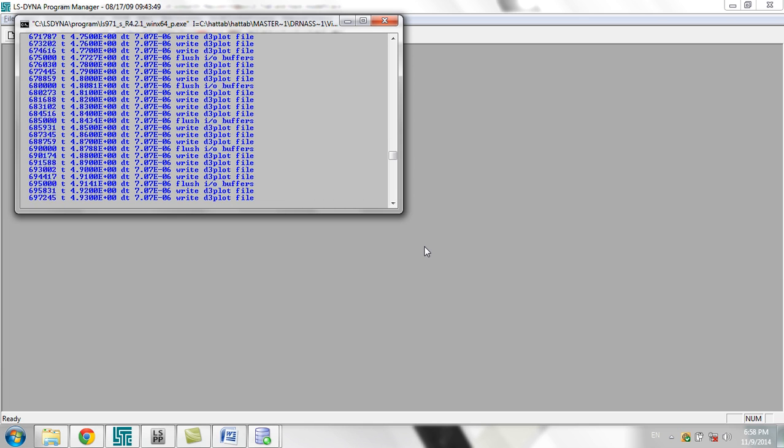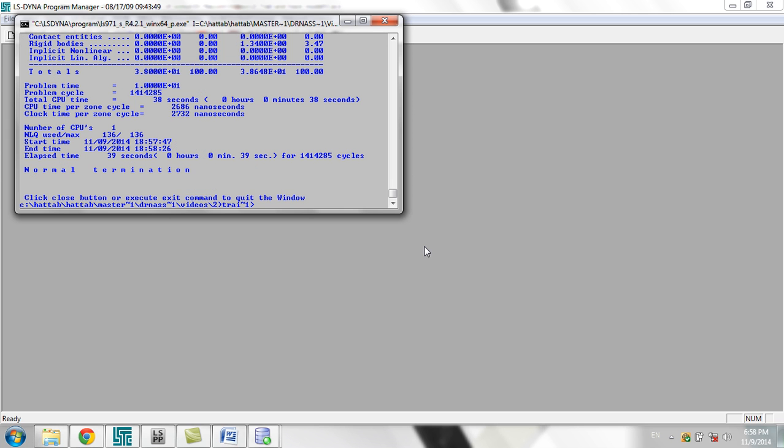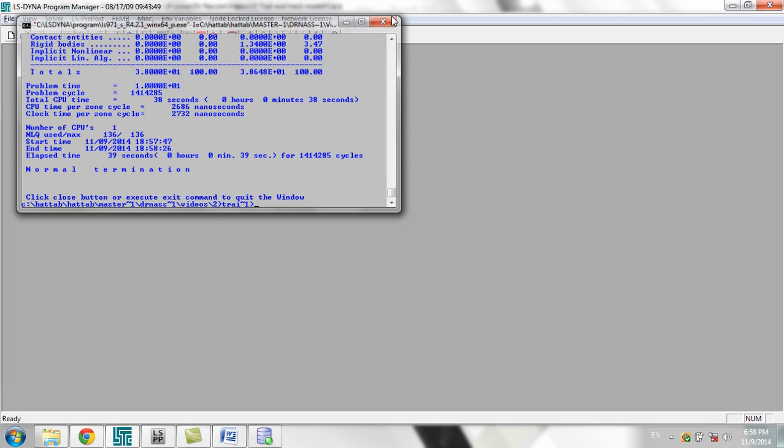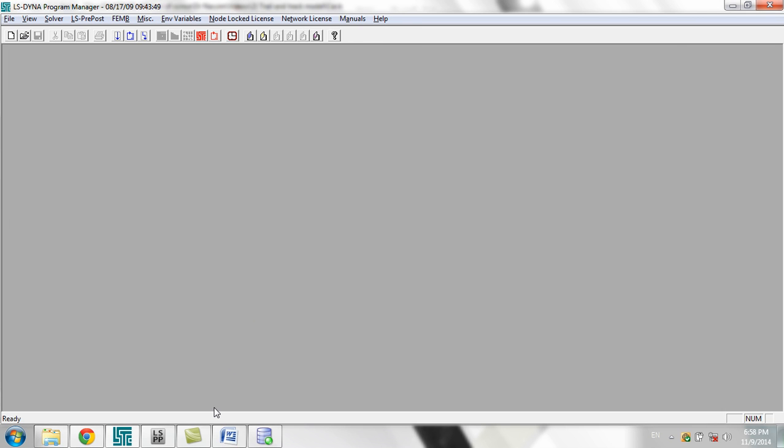And maybe someone asks, okay, there is no way to determine the time step except making trials. For sure there are some formulas. We will discuss this later, but it's a little bit complicated, so I prefer to do it just by trials, and you can see that by the third or fourth time you can reach the correct value. For sure, if you have a very complicated model, then you have to ensure from the first one that you have picked the right time step.